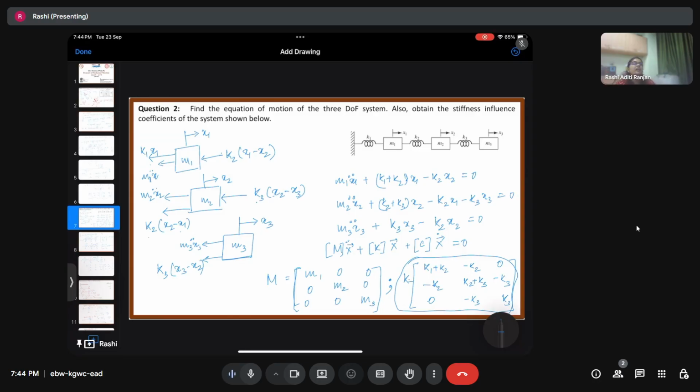The other two do not, which means I can write the solution in terms of only one frequency. But if I want to write the general solution, it will be an amalgamation of the three frequencies. That is why we find the modal frequencies and the mode shapes: if we know three independent solutions, independent because they are not dependent on the other two frequencies, we can write the closed form solution for any general case as the linear combination of the three parts.